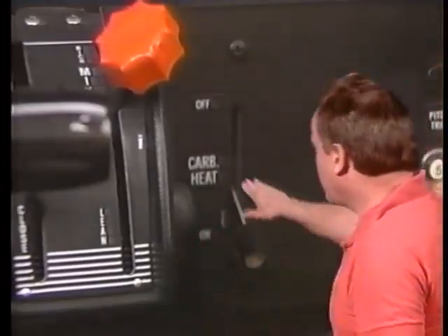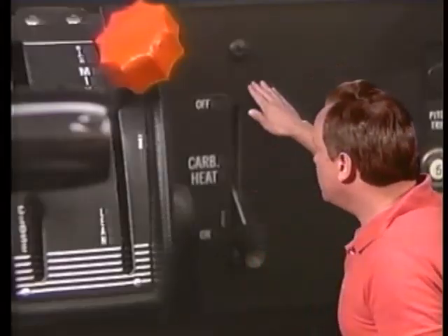Now, when operating an engine, the application of carburetor heat will affect the fuel-air mixture. How? Well, if you apply carburetor heat, as I said earlier, it enriches the mixture until the automatic mixture control on some engines can make a compensation and will decrease the weight of the fuel-air charge. But generally, what you need to know is that when you apply carburetor heat, you enrich the mixture in the engine.